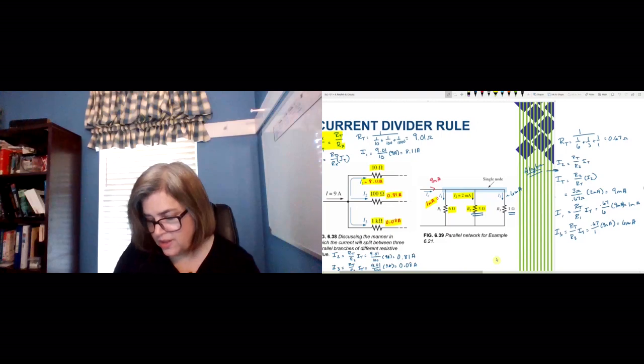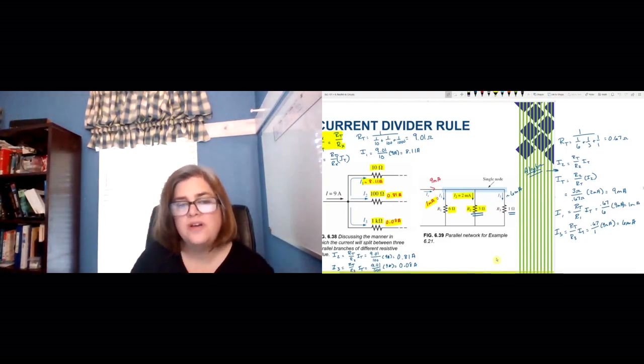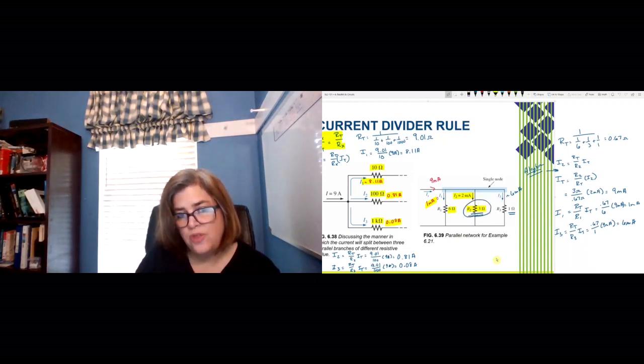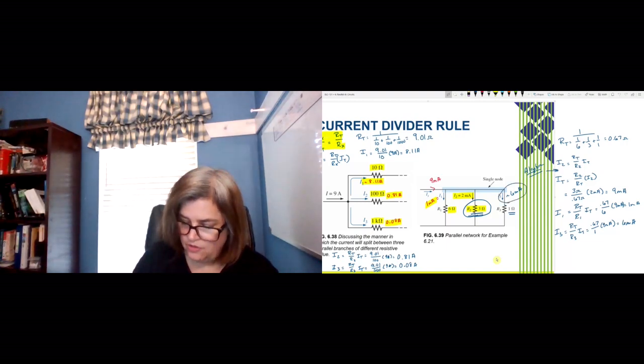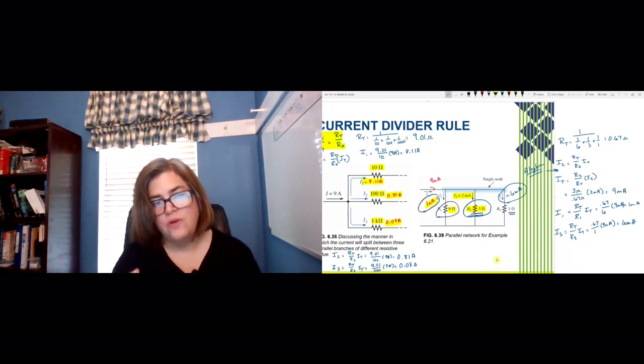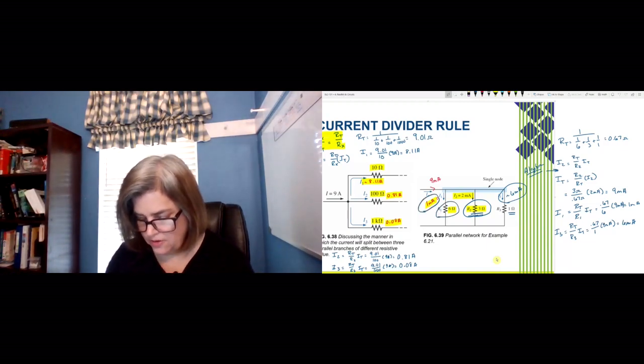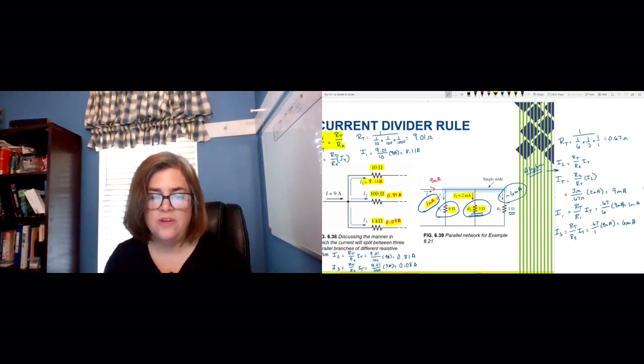And we didn't even really need to do a lot of the calculations because, like I said, if you have a 3 ohm resistor showing that you have 2 milliamps through there, a third of that resistance will have 3 times the current, and twice the resistance will have half the current. So once you start seeing these relationships, I think this will get a whole lot easier for you in doing these calculations.